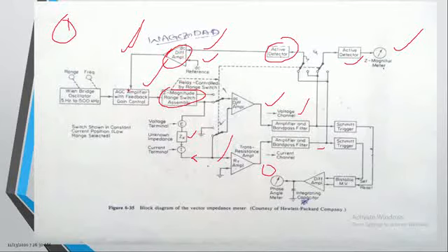Based on this value it is adjusting the gain, and because of that the impedance range is shifted. Like that, we are able to calculate the impedance magnitude by using this particular output. But we are interested to know whether the unknown element is capacitive in nature or inductive in nature. So for that, you are supposed to take the phasor diagram.